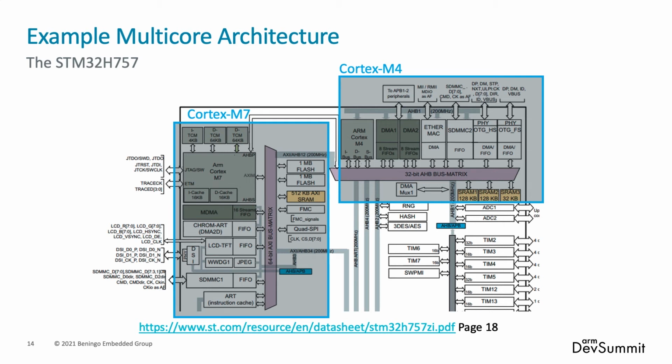And this is perhaps one of those things that, at least for embedded software developers at first, you just have to get used to, is the idea that you have two separate cores. Two separate cores literally means if I want to debug my system, I have to load code onto the first core, and I also have to load code on the second core. And then generally speaking, you'll find that you just debug one core at a time. But you do have to set up your debug script so that you can load code for both. Otherwise, you might not be able to fully test your application.